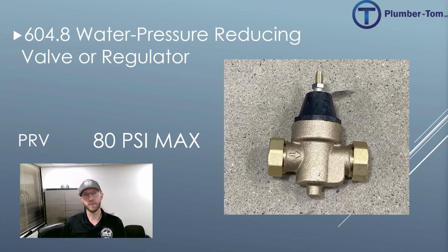So what happens if the pressure is too high? 604.8 goes over pressure reducing valves or regulators and states that where pressure within the building exceeds 80 psi static pressure, we talked about static, then you would need a pressure reducing valve.